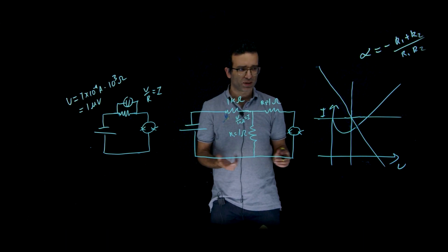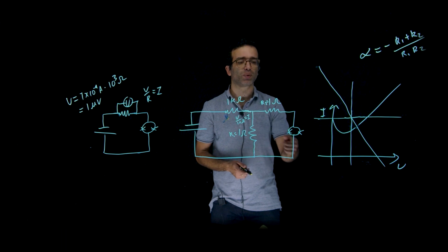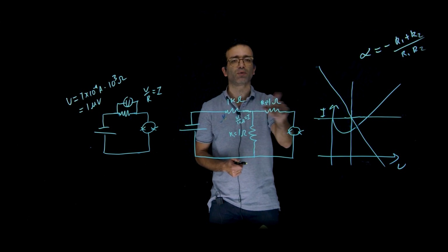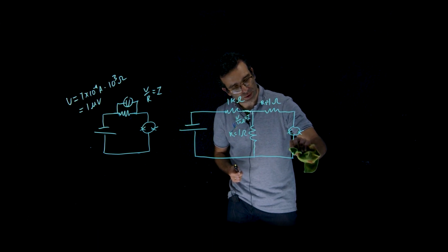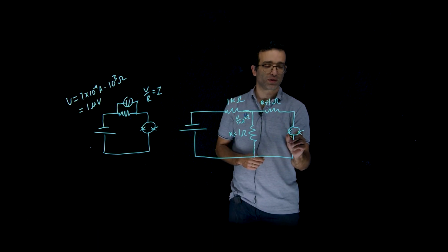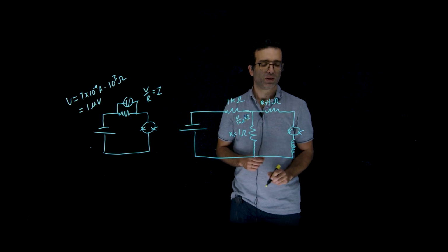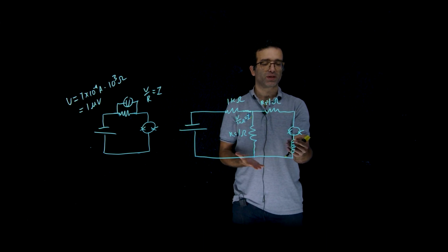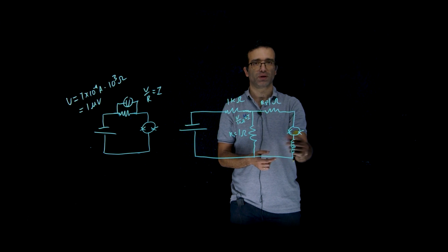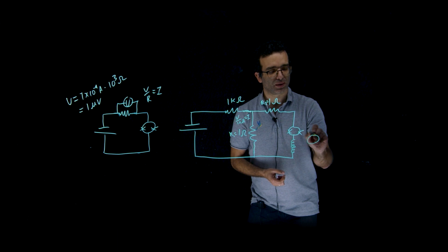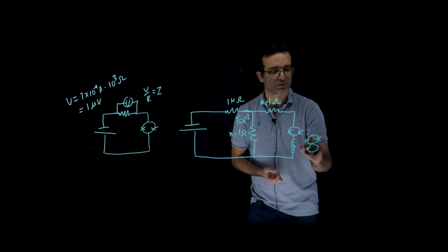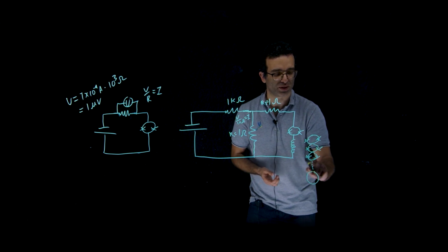So what is the trick? How can you measure the current without adding any resistance to this loop? The trick is to add here a superconducting coil, and this coil will generate some field. Once the current passes here, it will generate some field, and this field will generate flux into an array of SQUIDs. And I will just draw a couple of them, but you can have, let's say, 100 SQUIDs.